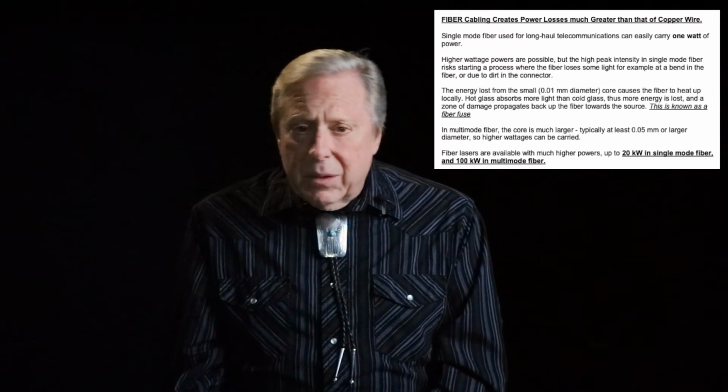Since a multi-mode fiber core is much larger, typically 0.05 millimeters or larger in diameter, higher wattages can be carried on it. But you need to worry about that because those powers can go up from 20 watts in a single mode fiber to 100 watts in a multi-mode fiber. And if you're also having a transient event like EMP, that makes the plastic turn white and it blows out the transmit and receive. So all the things you were told, oh, it's this, it's that, are not true.